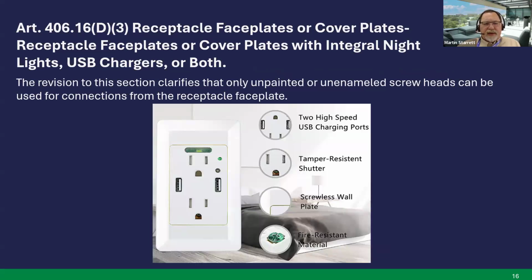Article 406.16(D)(3). We were seeing people increasingly adding these type receptacles. So, receptacle faceplates or cover plates with integral night lights, USB chargers, or both. The revision of this section clarifies that only unpainted or unenameled screw heads can be used for connections from the receptacle faceplate. I will say most of these faceplates are the snap type.